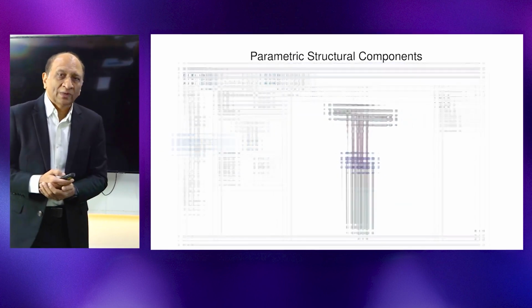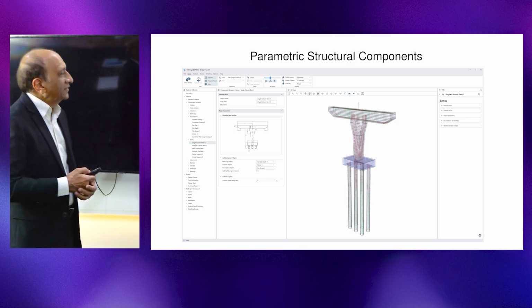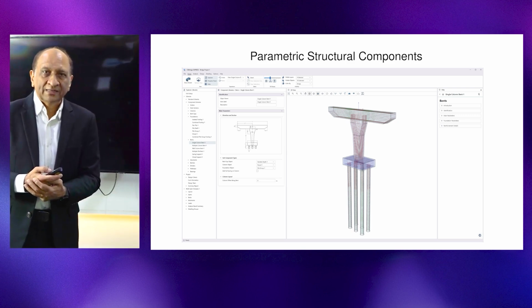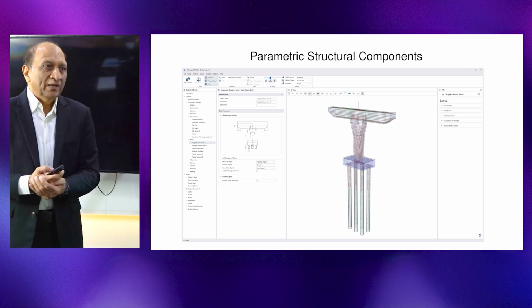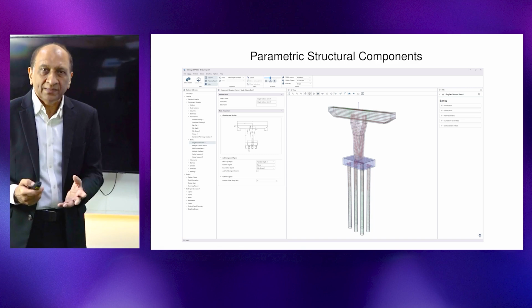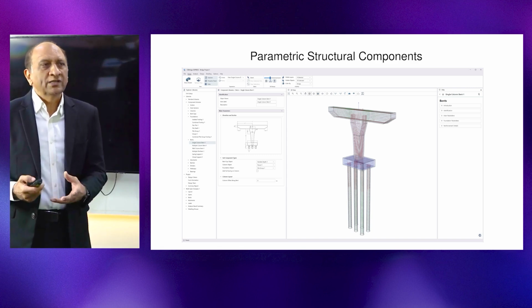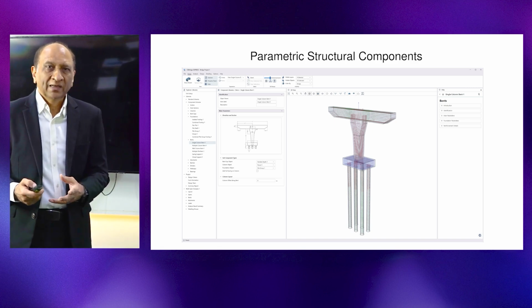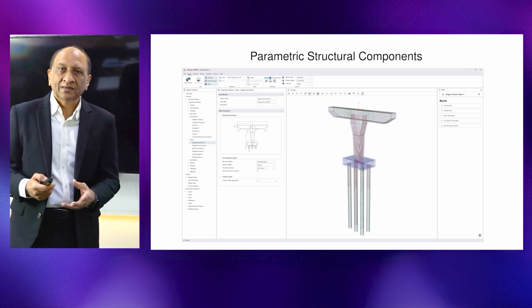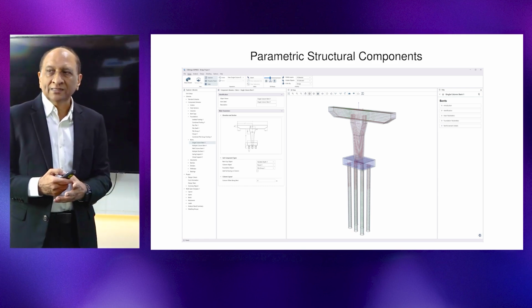Then we demonstrate this through one of our programs that we are developing called CSM Reach Express, and that is based on a completely parametric BIM system. That means we define the components of the bridge in advance, complete with the reinforcement details as the starting point. Because we already know what it's going to look like mostly, maybe a few bars may change here and there, but 80-90% will just follow the detailing rules and detailing practices.